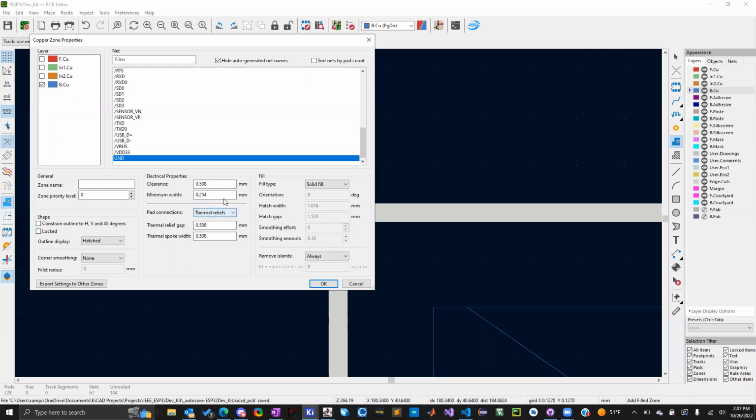We're gonna want the thermal reliefs. Actually, no, yeah, we're gonna want the thermal reliefs because for the components that are through hole, you're really gonna want the thermal reliefs to make it easier to solder pins. I haven't decided it. I might just make JLC PCB, I might just pay the difference to have them solder it on. Because we'll have the name tags to solder by hand and learn to do, which is simpler. But for the dev kits, I might just have the company do it. But the thermal reliefs will really help them and whoever's soldering those on, it'll make their lives easier.